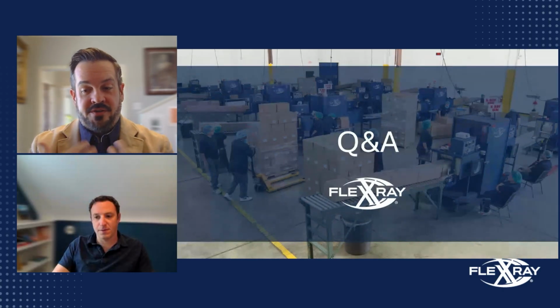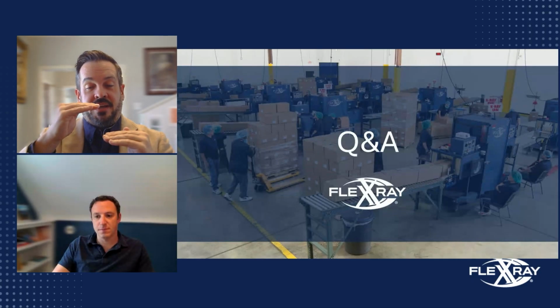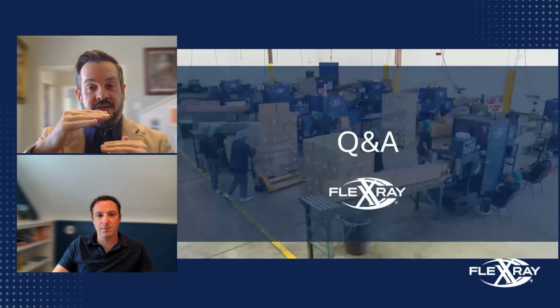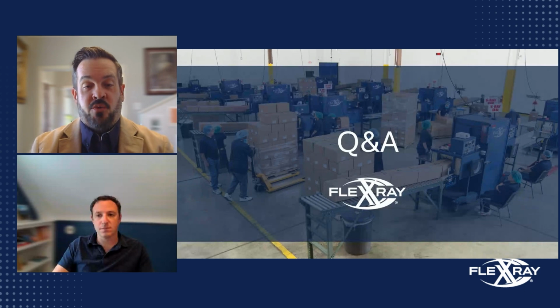So I'm just going to use some numbers for easy math. Let's say your product density has a grayscale threshold of 1,000, and the foreign object that we're detecting, say 1 millimeter of stainless steel, is at 2,000. Well, that's a significant disparity between product density and foreign object density. We're going to find that 100% of the time. There's no way that that can be missed.